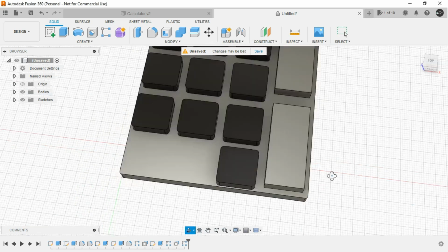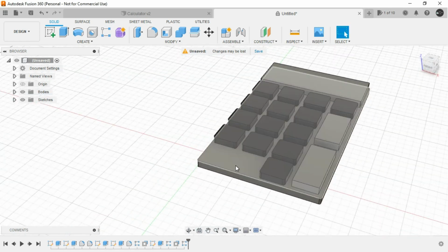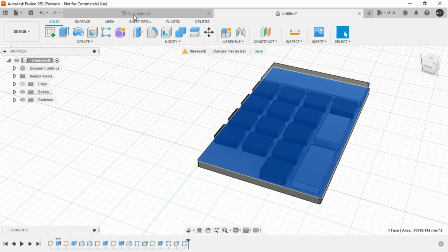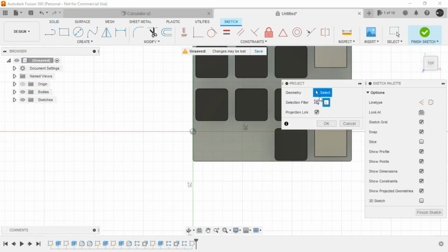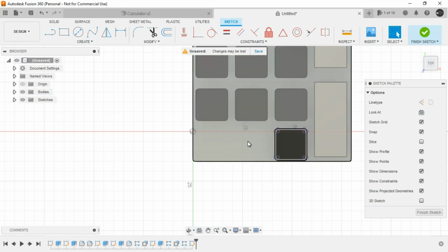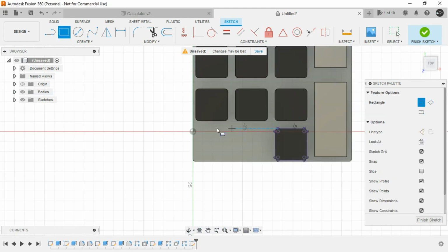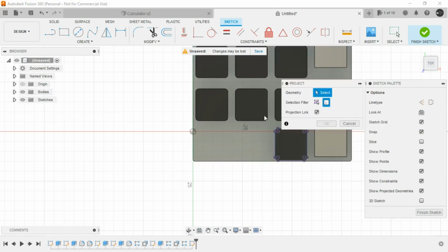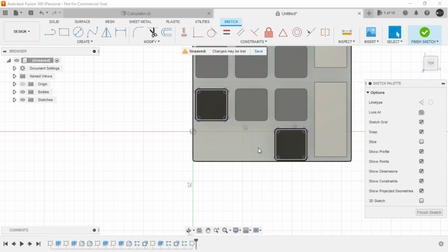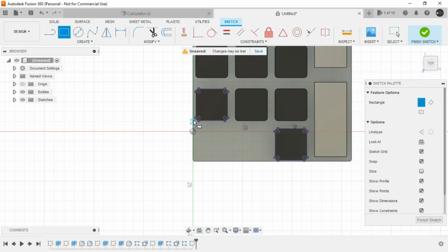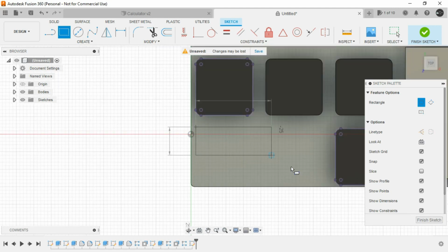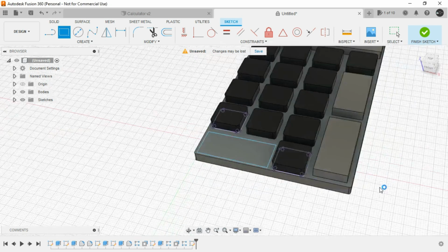Alright, click on OK. Now for the 0 number, this one we have to again create by sketching. Let's project this body, click on OK. Invoke the rectangle command from this point to OK. We need to project this one also. Invoke the rectangle command, trace this point also, somewhere from here and here. Finish the sketch.